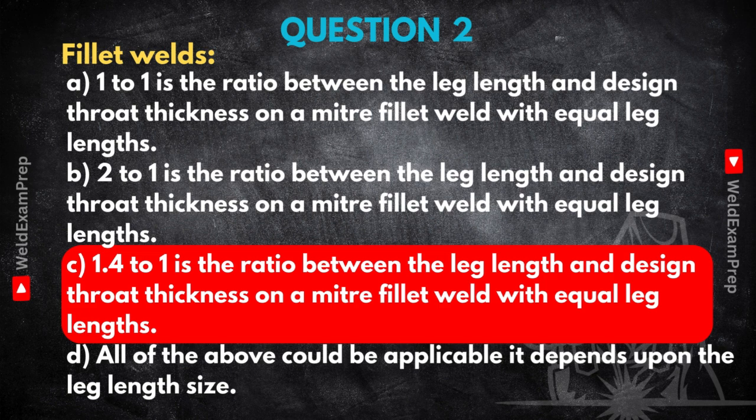So the common pitfalls may be just visually checking leg length or being a bit casual with the gauge. An inspector needs to be precise because that seemingly small geometric difference directly impacts structural integrity. It could be the difference between holding and failing under load. Wow, okay. So a tiny measurement error has potentially huge consequences. That really highlights the responsibility.